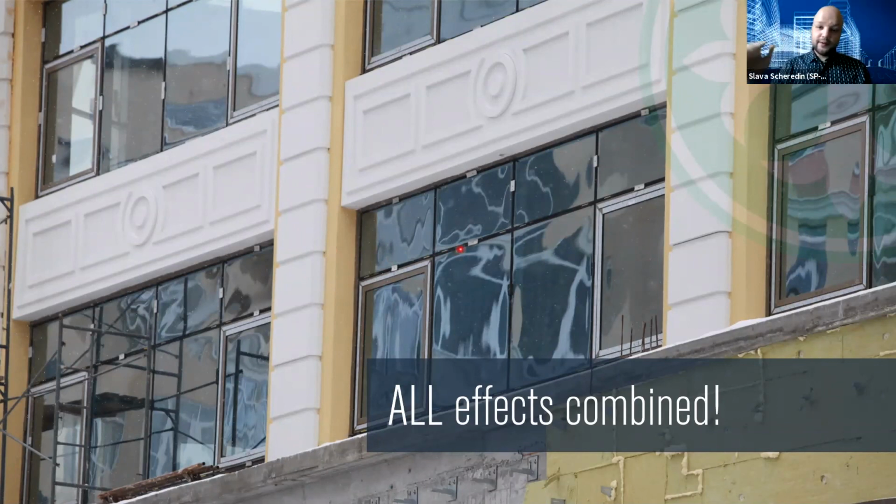This is very reflective glass in the winter, unheated building, very big distortions, improper positioning of the glass in terms of roller waves. And in the end, you have here some distortions from the facade clamping. So just about everything which can be done wrong is combined on this facade.